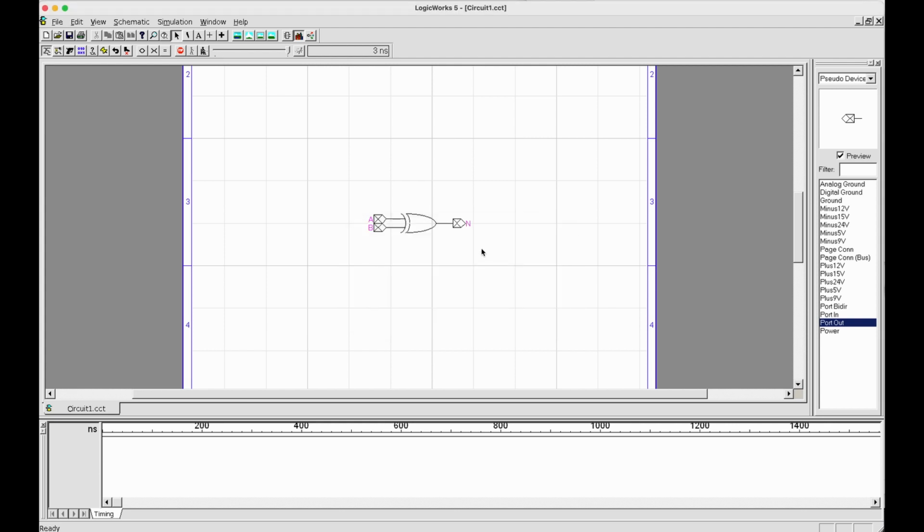Like we said before, you can implement MX in this particular manner if you do have an exclusive OR gate available to you. In this case, I've actually skipped the verification step, but in practice, you should always check for connections and check if this design actually works using binary switches and probes first. In this particular case, let's try to implement the same circuit without using the exclusive OR gate. Again, let's delete the exclusive OR gate and corresponding wires.